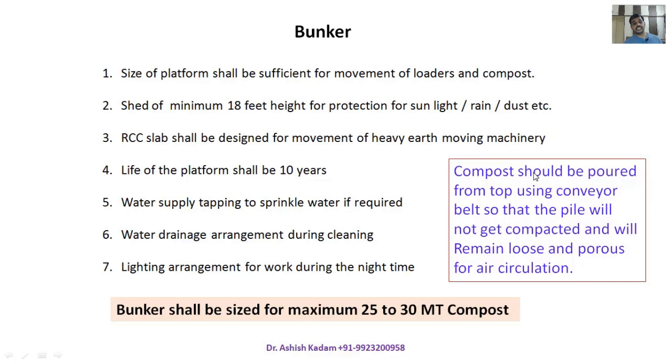Then sixth is the water drainage arrangement. Again, you have seen that when you are cleaning the bunker areas, the water gets accumulated below the slab of the bunker, and it becomes like a drainage pit, and then you have a colony of bacteria, and the water starts putrefying, and then you even get a very bad smell, and it damages the entire environment of the farm. So there has to be a proper drainage arrangement provided, so that after the cleaning, the water will flow easily out of the bunkers.